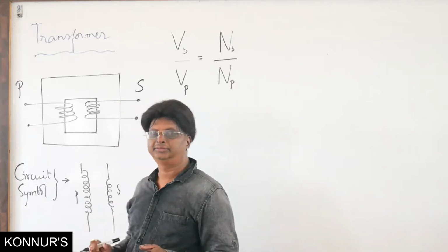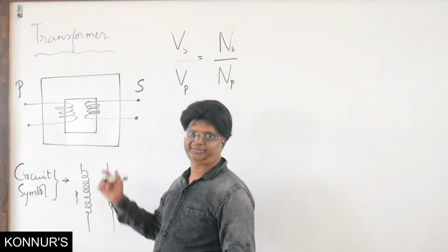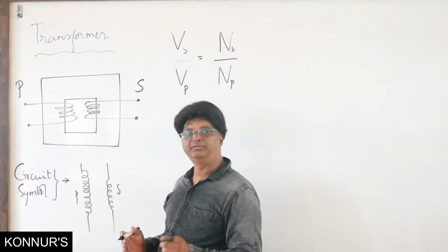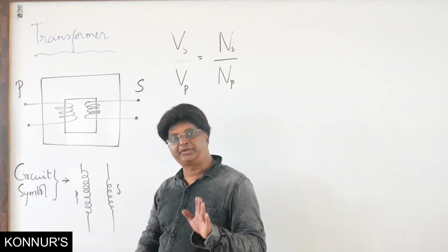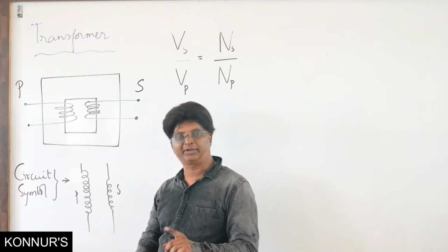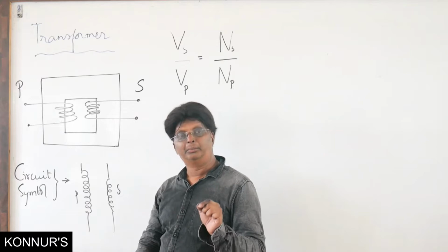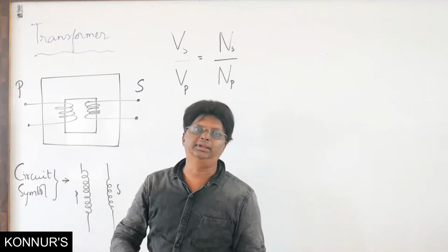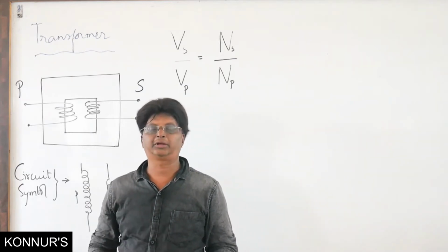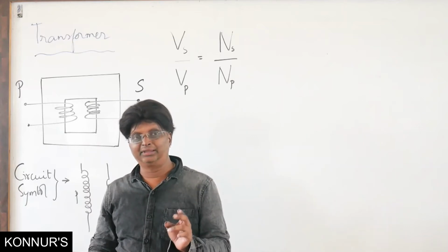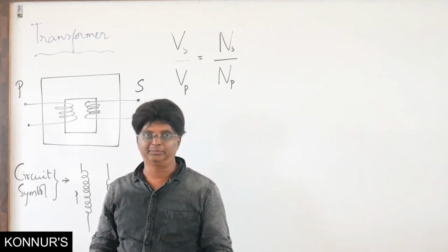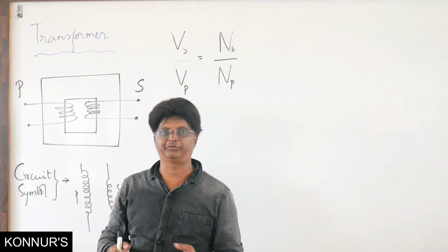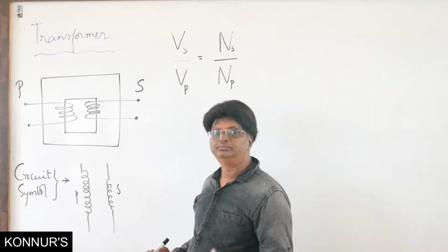So with such details, these are the two coils. We are showing it as a model, as a block diagram. In fact, do remember, when it is the case of mutual induction, for it to be the most effective, it is always the case that the secondary coil is placed inside the primary coil so that the flux linkage with the secondary is maximum due to the primary. So the secondary is placed inside the primary, that will be the case for the maximum or effective flux linkage.